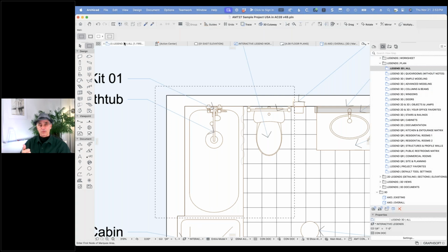It'll have the same look and feel. You won't have differences like, well, in this project, we did it with this line type, that's a thicker line than this project. Whatever inconsistencies. You'll have standard naming for whether it's library parts or wall types, etc. It'll be easier to find. You can have it in a folder structure, so you know where it is. So just think about how to organize your workplace in Archicad so that it's easy to find things, and as much as possible, they're done ahead of time.